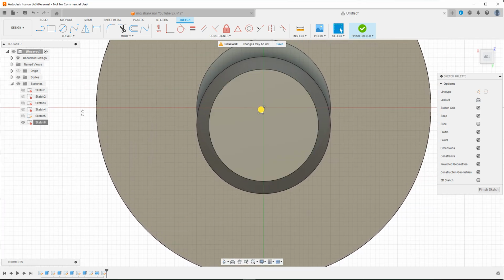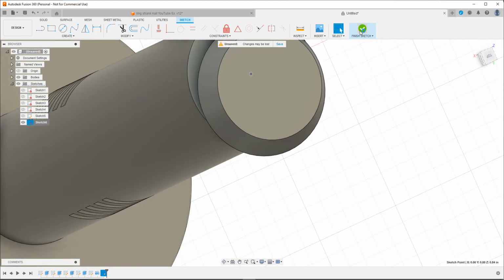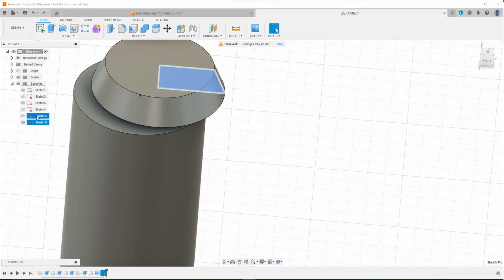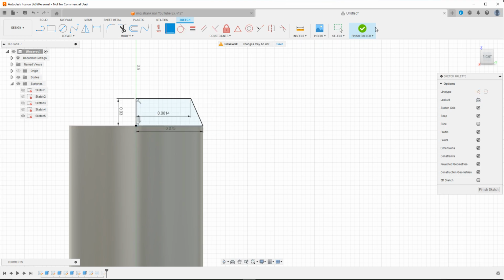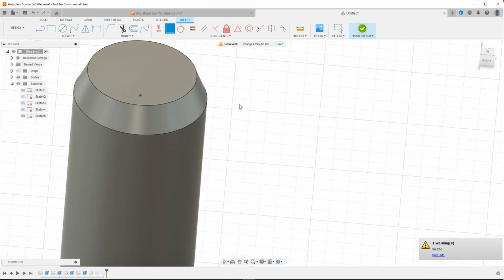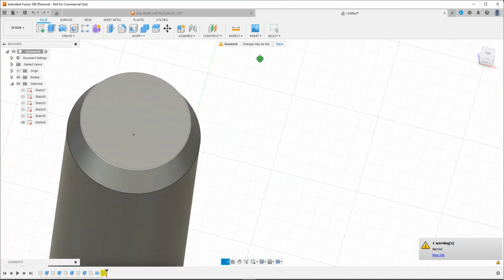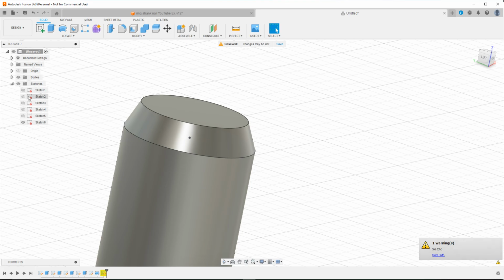Definitely a good learn along episode, that's for sure. Okay, I think that's constrained. Let's go back to sketch 5, edit sketch, and we're going to go to coincident and pick this point and that point. Now we should be good. Okay, good. And we have the red locks over here, so that's good.